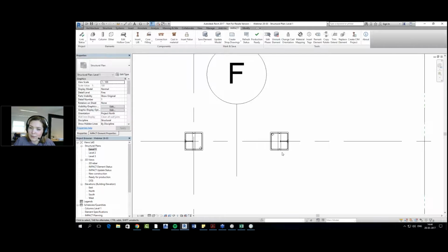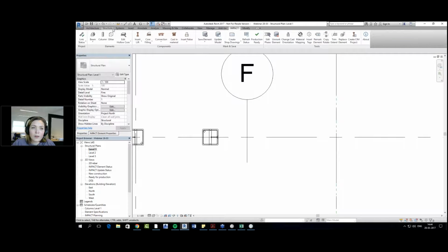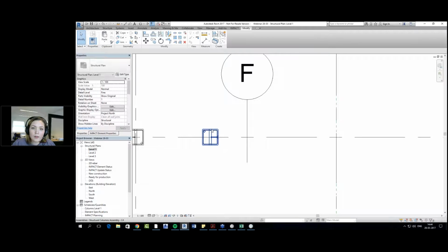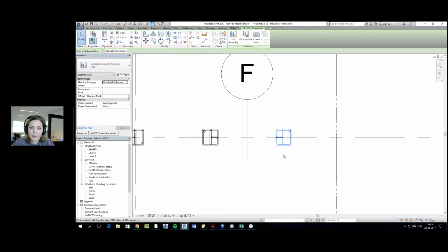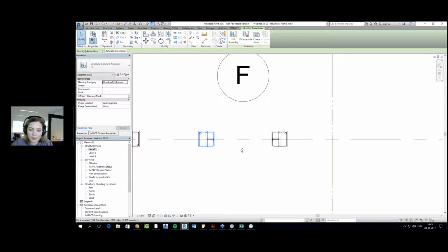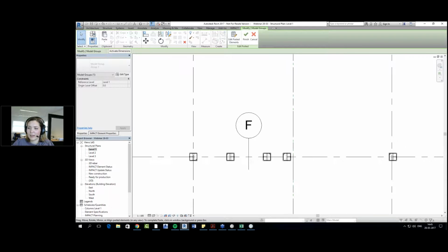But if you don't want to have it rotated, you can just use simple mirror function in Revit. So what it does actually then, it takes the same element. If I go to modify, and then I kind of mirror it. So it mirrors in the axis, in the middle axis. Or I can just simply say copy paste and just paste it the same way it is right now. I hope it answered the question.